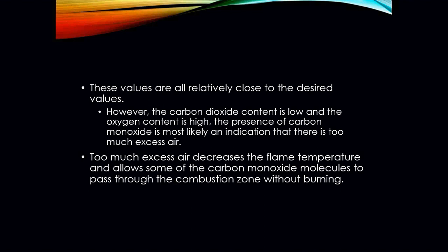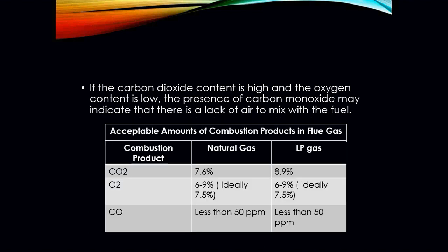Remember, go back to that combustion triangle. We have to have enough air, enough fuel, and enough heat in order for us to have a complete burn. If one of those three is off, you're going to have an incomplete burn and you're going to run into issues. So if the carbon dioxide content is high and the oxygen content is low, the presence of carbon monoxide may indicate that there is a leak, a lack of air to mix with the fuel.